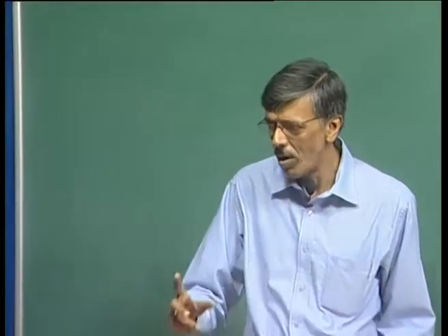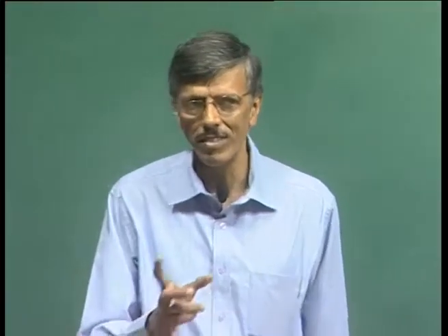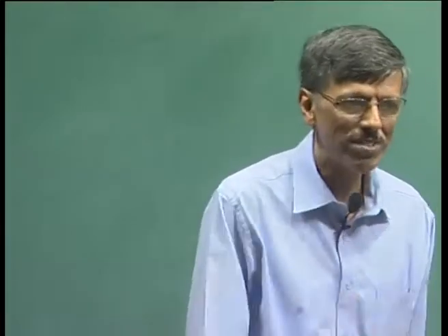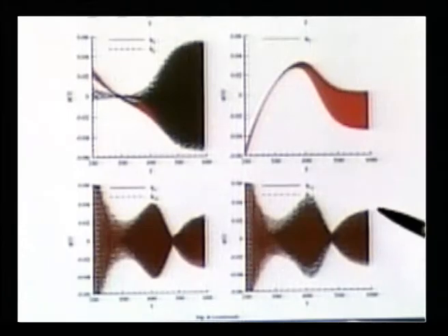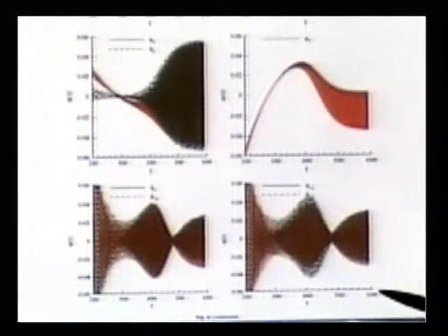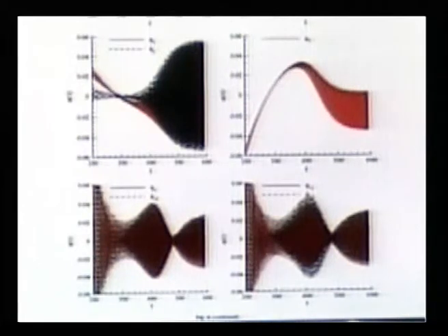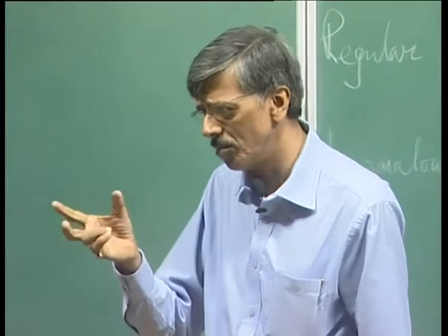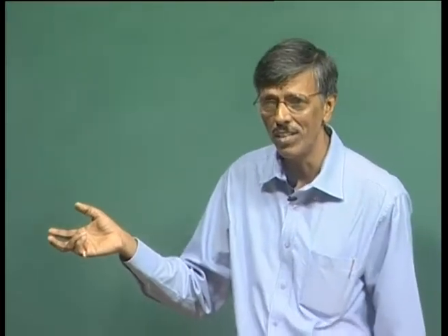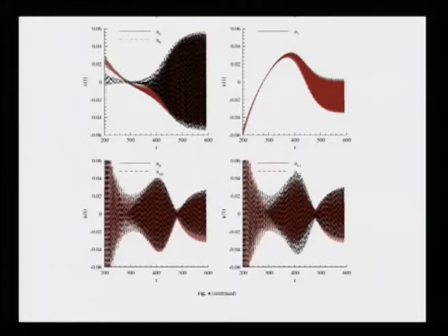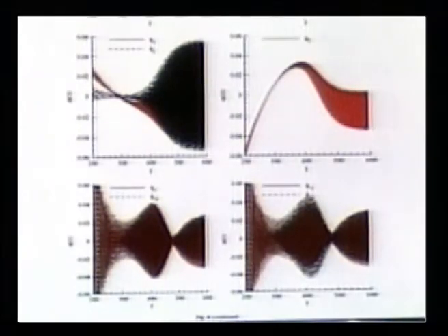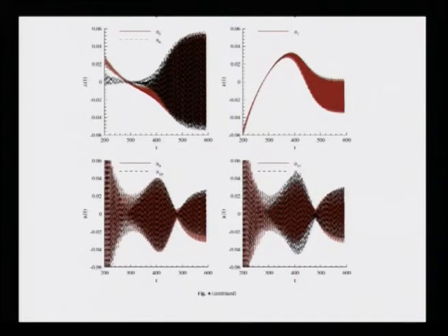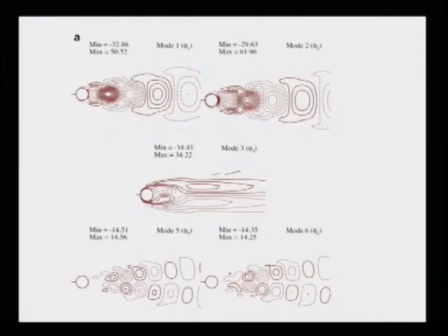And then of course, the moment you decide upon the sampling rate of POD analysis, that restricts you to what you are seeing. And tell you what, these kinds of simulations have been done to pick up these kinds of frequencies. What you are seeing here, we have shown from 200 to I think 600. So here the time interval, the sampling rate, is of the order of about 0.01, 0.02. So you can imagine the volume of data that you will have to handle to do a POD. And if you do not do it, of course, you will not pick up all these frequencies. So you must pay heed to the requirement of resolution, and this is a very, very vital issue that we must talk about. Now, these are some of the things that we have seen for our circular cylinder.